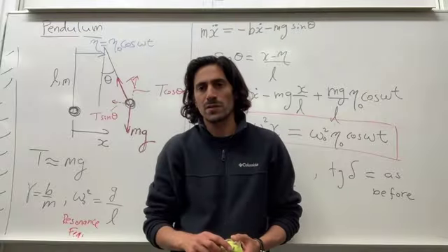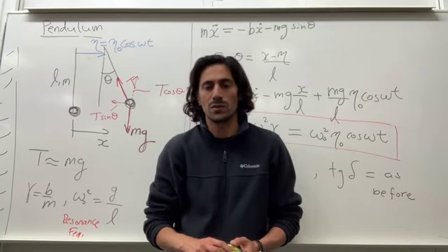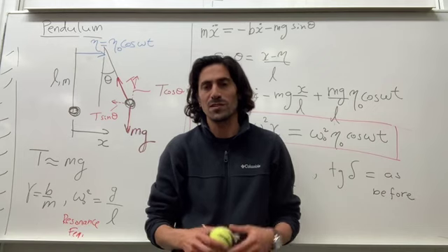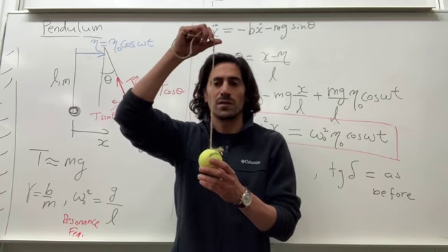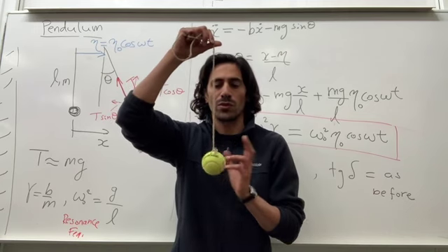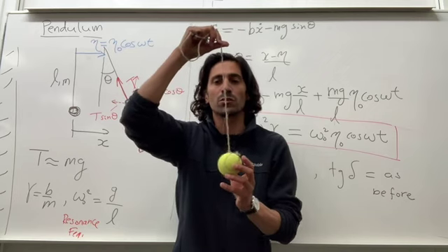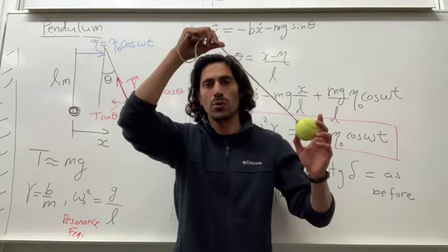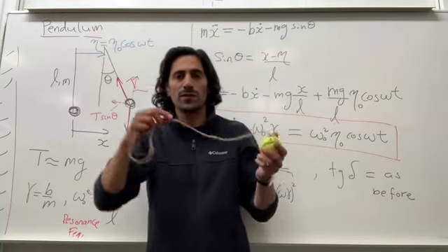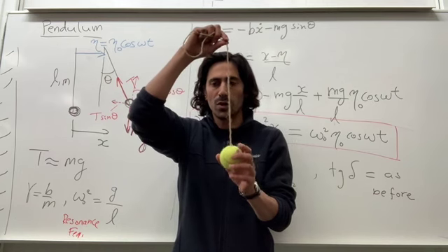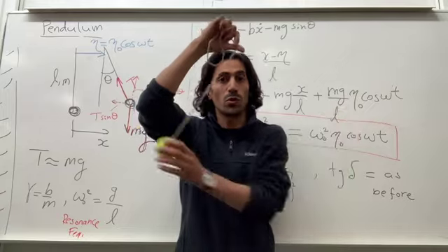If I drive it at the resonance frequency, then just as before, you'd have the same amplitude that we had with eta 0 when I did it very slowly, but with a factor of Q. So if this has a Q factor of 5, and the amplitude was eta 0, now it would be 5 eta 0. So it would go really large.